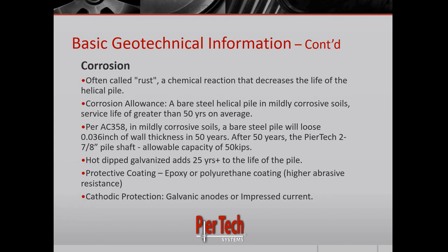And then the second is an impressed current. So that would be typically done on piles that are in the ground and are exposed, have a very large exposure surface area. So very large piles potentially, or areas where welding is being done, or there's some sort of DC current in the ground. So that's when you would potentially impress a current on those piles.